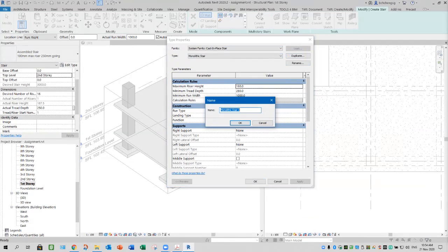Staircase is considered a system family. If you take this and edit, what happens if you make a mistake? You might not know what the default or original setting was. So it's good to leave the original untouched. When the other one is damaged, you still have a spare.